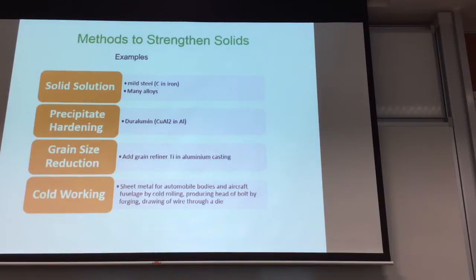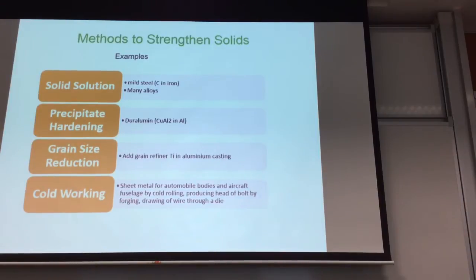If you look at your stress strain curve, you start from zero stress, you reduce the thickness, so basically you apply a stress or strain up to that point. After it passes through a roller, what happens to it? You will want to spring back, right? Because of the elasticity. So you will follow this curve.